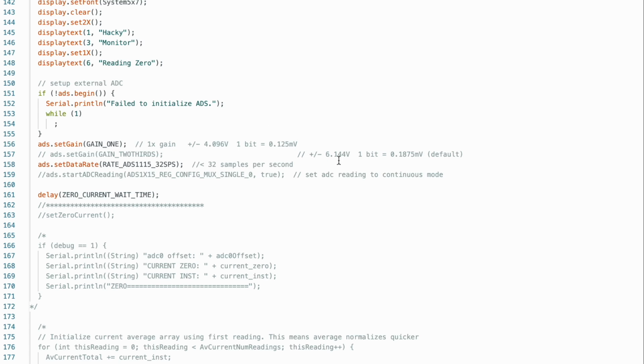You can also set the ADC to read in continuous mode and use the interrupts. This is one of the things that I don't think the Adafruit library seems very good at, and I need to do a bit more. There's a few things on the forum about it, but hence I might in the future change the library and play around with it, but for the moment it's working well enough to get to this stage.